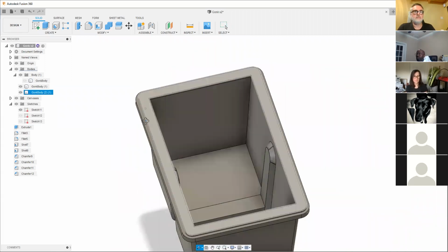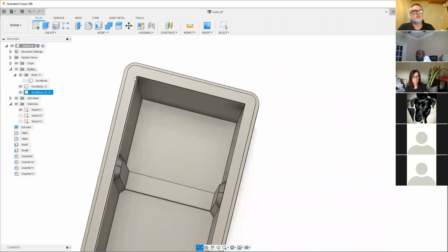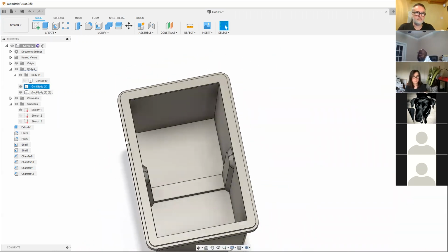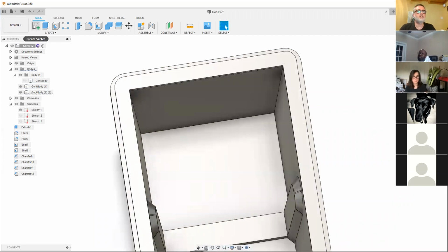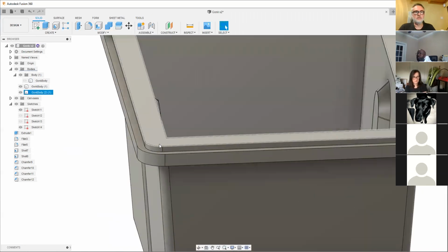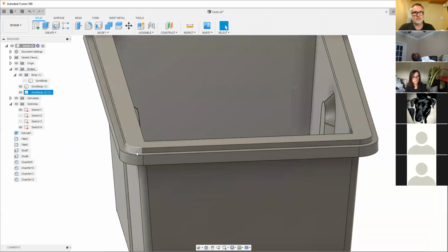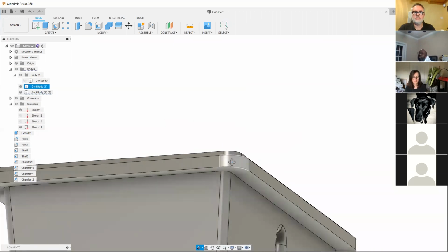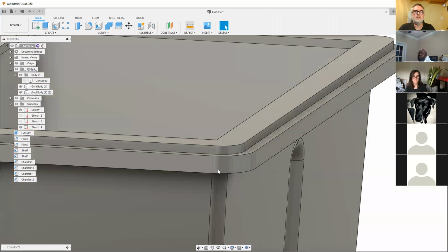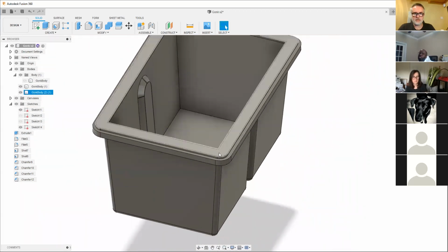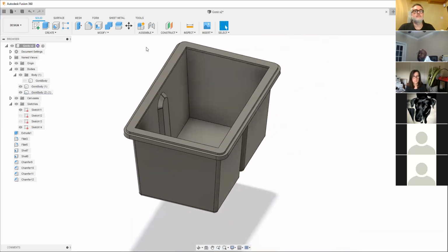Okay. Now, the other thing, what I'm thinking on this one is I'll perhaps put some filament peg holes on each corner so that these things line up. So what I'm going to do with that is I'm going to go back into sketch mode. Actually, before I go into sketch mode, I'll show you. So what I want to do is create about a 2.1 millimeter hole in each corner that doesn't go right the way through this. It just goes to within a millimeter or so. We've got 4 mil to play, so about 3 millimeter deep, which will let me make those. I can then use filament pegs to align this when I print it.